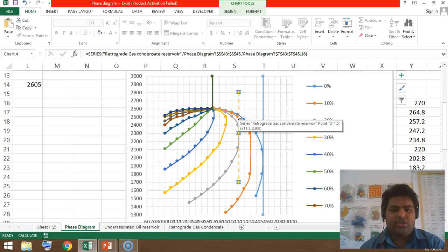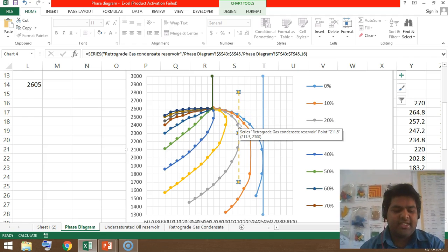So now what will happen as we move further? This liquid percentage would be increasing. Now the thing is that there is a liquid separating out from the gas in the reservoir. That liquid will stick to the pore walls. In any porous medium, a liquid moves only after it achieves a certain minimum saturation. We call it the residual saturation or immobile saturation. Until that saturation is achieved, the liquid phase will not move.